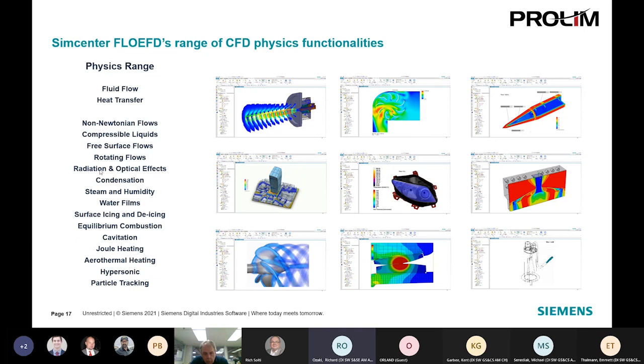Just going to highlight a couple of things. So rotating flows, for example, if you do have fans, impellers, propellers, where you're driving air or water, we can simulate those. Condensation is a new one for us. So being able to understand fluid films and how they burn off, right? If you don't want water forming on the inside of your brand new BMW's headlight or tail light, right? We want to avoid that. Filling and emptying simulations.